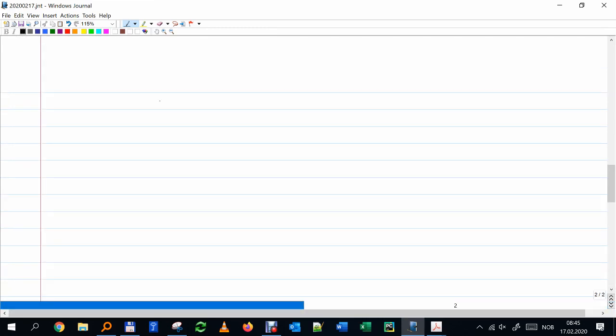Now, on another topic that I thought we have to complete a bit: how to choose tubing size. Okay, how do we choose tubing size? It's a big decision when we are designing a field, to see what diameter of tubing we have to put on the well. So what factors do we have here? How do we decide which tubing size to use? Well, one is the obvious, right? We simply want to maximize production.